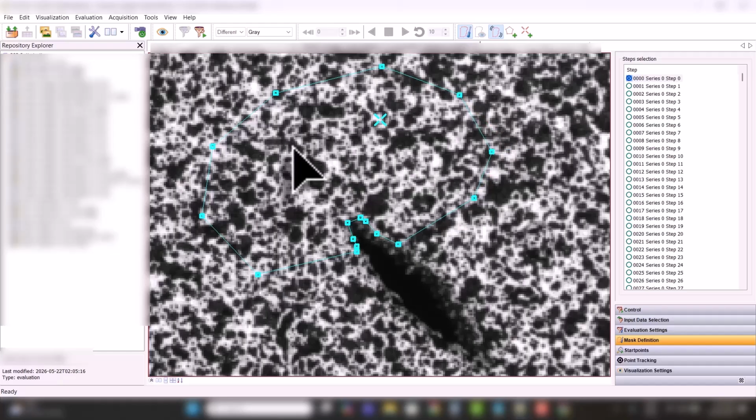And so the general idea is the same idea in that smaller facet sizes are going to be useful so we can get up close here to the notch tip. But what's also coming into play, it wasn't an issue here, but for another test at a higher load, you could be having necking occurring here. So speckle pattern breakdown. So how do you deal with it if the speckle pattern is breaking down a little bit?